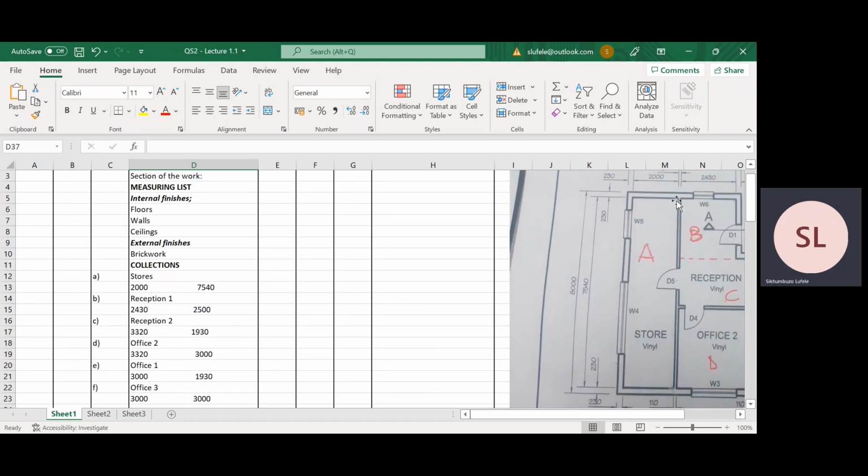Then also we've got another wall there. We've got a wall here where we need to put the skirting, and also a wall there where we need... sorry, not the skirting, I'm making a mistake here. This is the whole area where you'll have your screed. I'm correcting myself. You'll have your screed here, you'll have your vinyl tiles here, and also your polishing will be here.